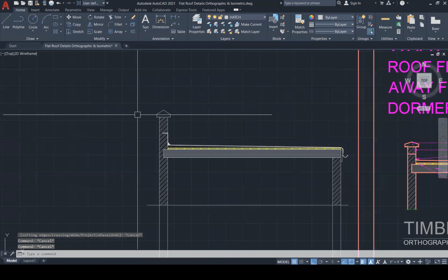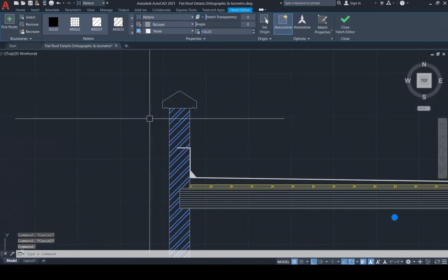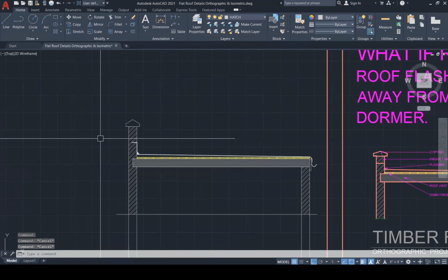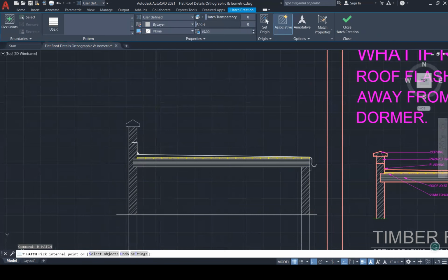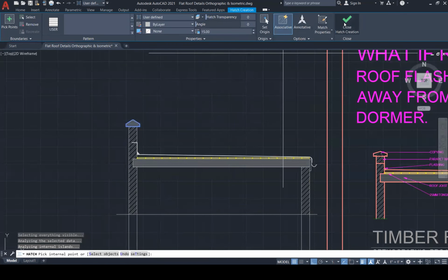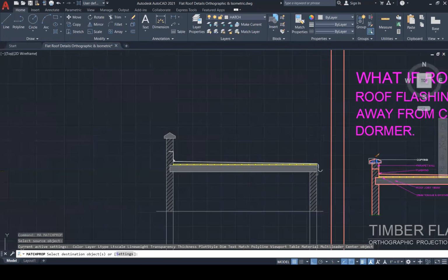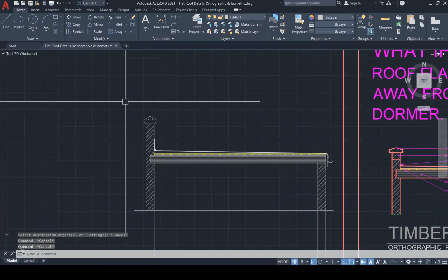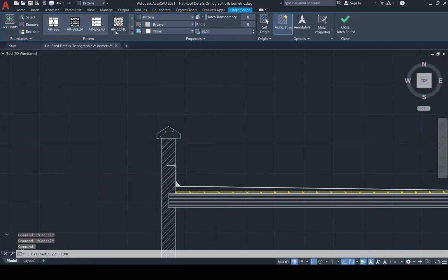That's the coping there. Nothing more to it. That material would be solid concrete. So just watch that. Then I'm going to match it. And match drop. Grab the material from here, and then put it there. That's solid concrete there. I mean, the solid concrete, I use air con. My scale is 15 and I do nothing with the angle. I don't bother changing the angle on that one.